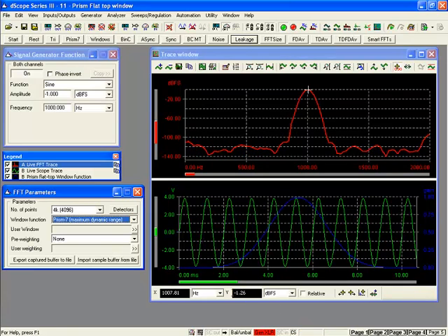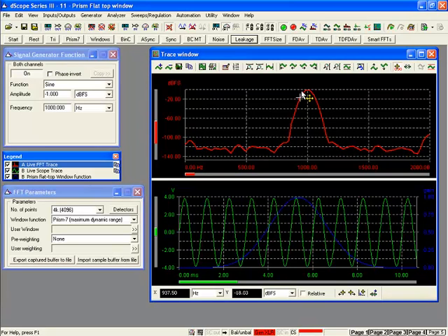And the reason for that is that the energy is leaking into adjacent bins, and we therefore have to integrate the energy over this entire range of, in this case, ±7 bins if we want to put an accurate number on the energy contained at 1 kHz. So that again illustrates why you can't just simply look at the FFT, put a data point or a cursor on this data point and say, yes, that's -1.26 dBFS, because we know now that it isn't.